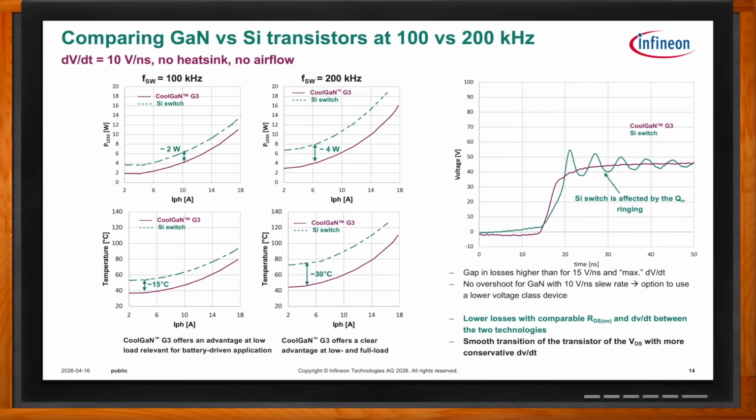of power loss. So what I'm saying is, yeah, you could run silicon at 100 kilohertz and run your motor, but now that benefit is reduced significantly because my motor power loss went down, but the drive power loss is substantially more. I think the other key takeaway here comparing silicon versus GaN is on the right-hand side, where we look at the switch node voltage of each of these technologies under the same conditions.